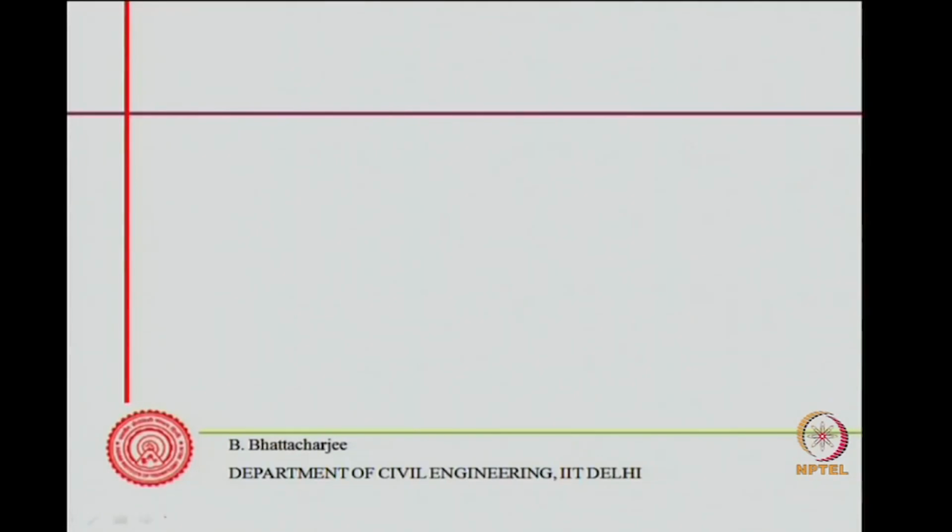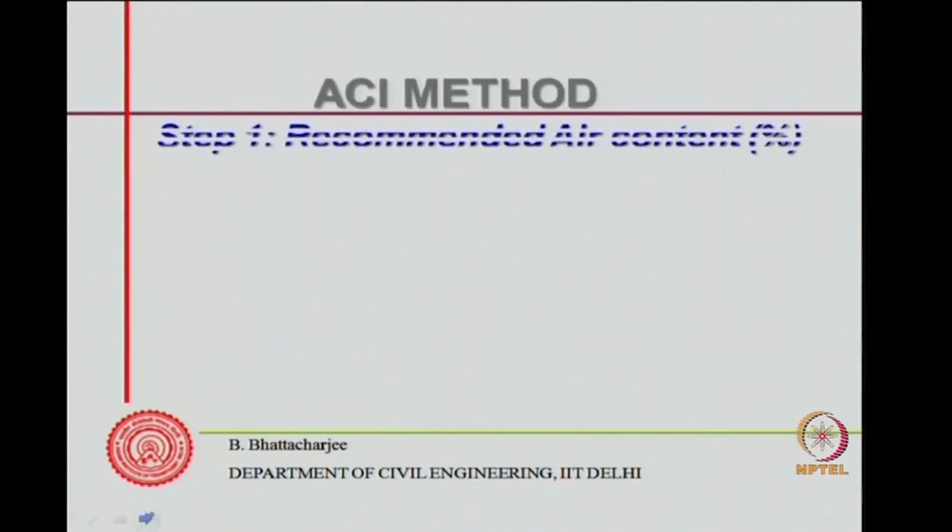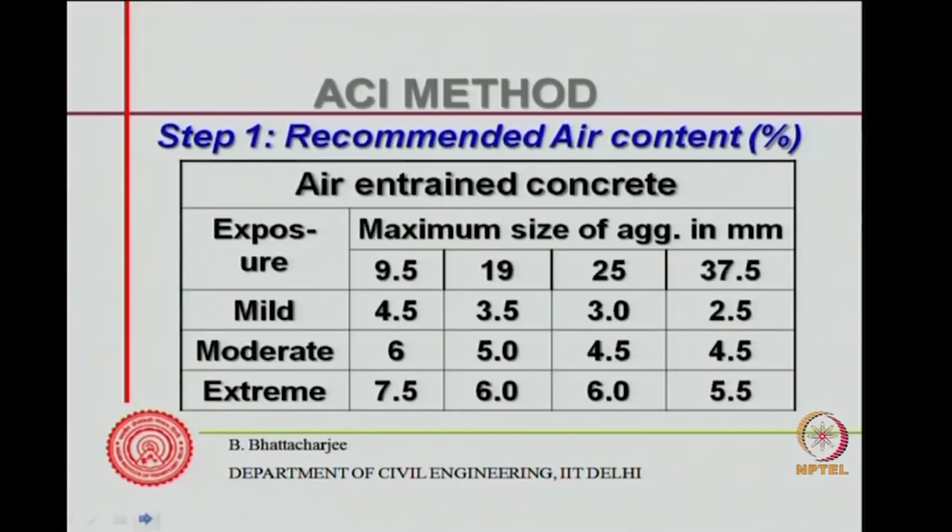For air entrained concrete, however, this will be much higher, and that would depend upon the dosage of the air entrainment. Now, this table suggests the minimum recommended air content for different exposure conditions.